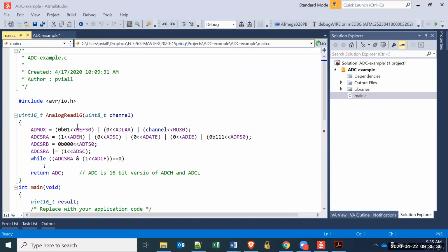Yes. Okay. All right, last time, just to review, we had done this code looking at how the analog to digital converter works. And we wrote a routine. We had looked at all of these flags in each of these registers for the ADC. We are using the ADC in polling mode, not interrupt mode.